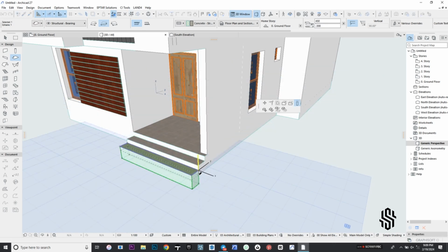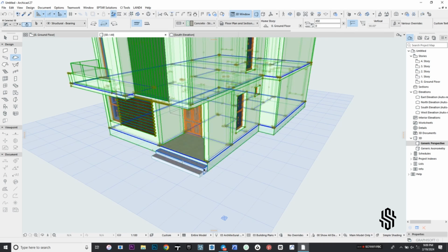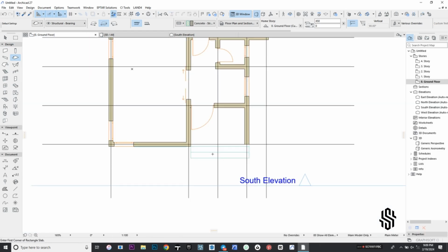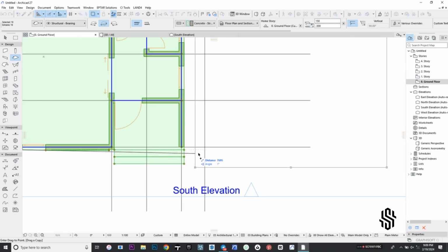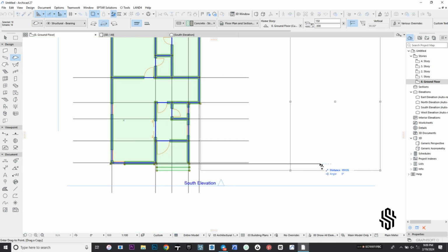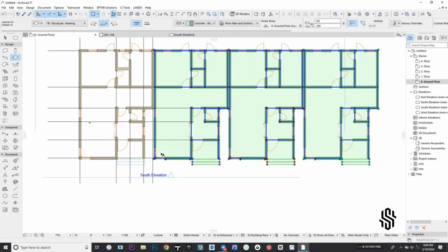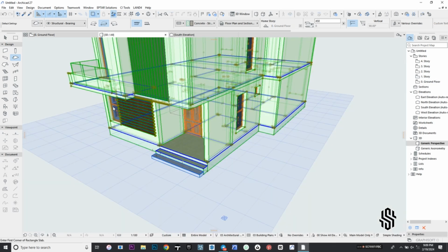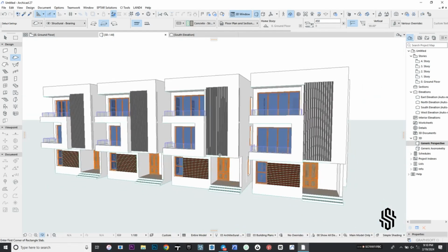Now I'll select the main building and then this new 2 slab and group them together. You can see it appears on the ground floor. I'll hit Ctrl U and hit OK. Select it and go all the way up to select this top, so that I'll have a reference for these 4 terraces. We have successfully multiplied the building to 4 units of terrace.